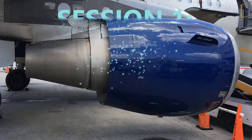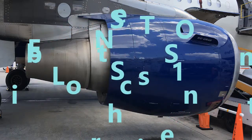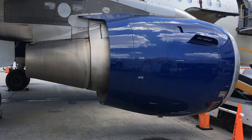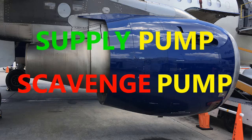All right, and of course, the lines are going from the oil tank. And by the way, from the oil tank you've got filters, because you have to make sure you have filtered oil along the way. But then you have those tappings in the line, because why? We need to get the oil distributed to the different areas where it's needed. And therefore you have pumps, different pumps throughout the circuits. You have one supply pump I mentioned earlier in the oil tank, because you're going to need to get that oil moving and then pressurized.